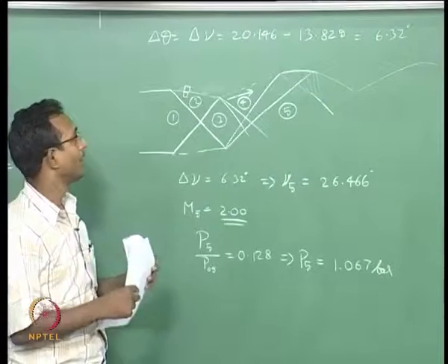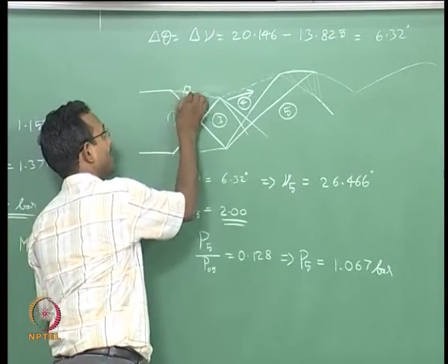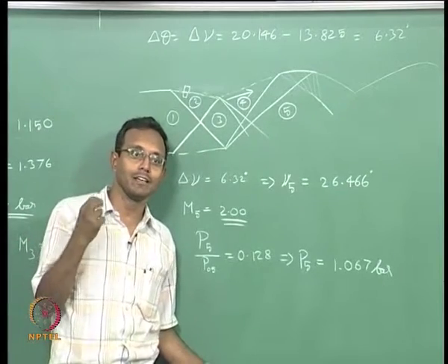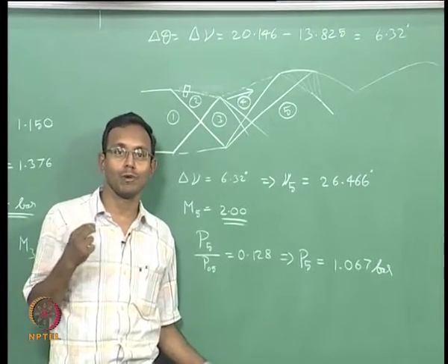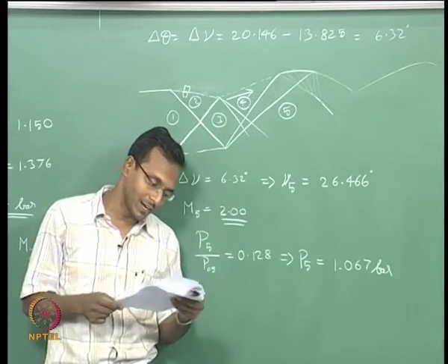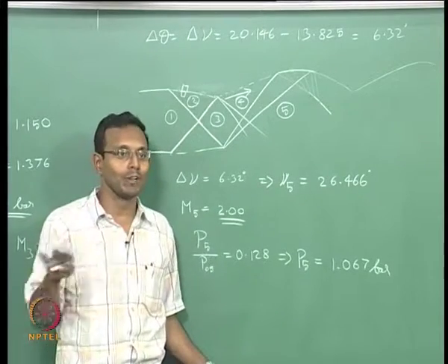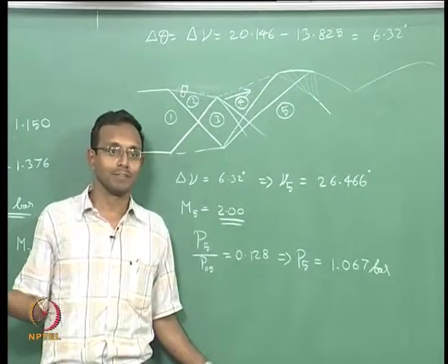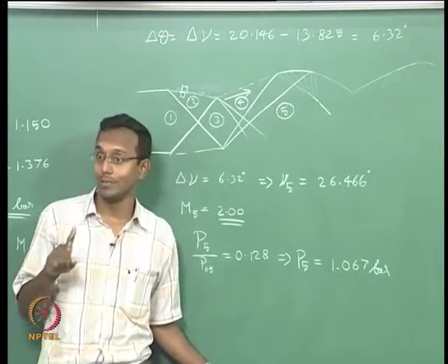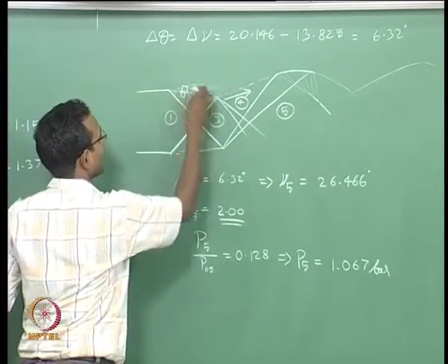So you are going to have that special case called a shear layer. There is that one layer of fluid elements where you have a very high concentration of vorticity distributed along that line. And because of that, you are going to have viscosity in real life. Now I am no more in my ideal gas dynamics world. I am trying to include viscosity in my gas dynamics. If I include that, then you will start having some momentum mixing happening across this region.